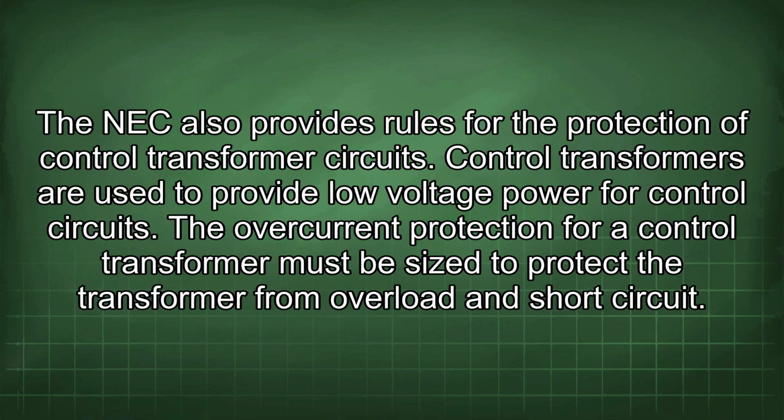The NEC also provides rules for the protection of control transformer circuits. Control transformers are used to provide low-voltage power for control circuits. The overcurrent protection for a control transformer must be sized to protect the transformer from overload and short circuit.